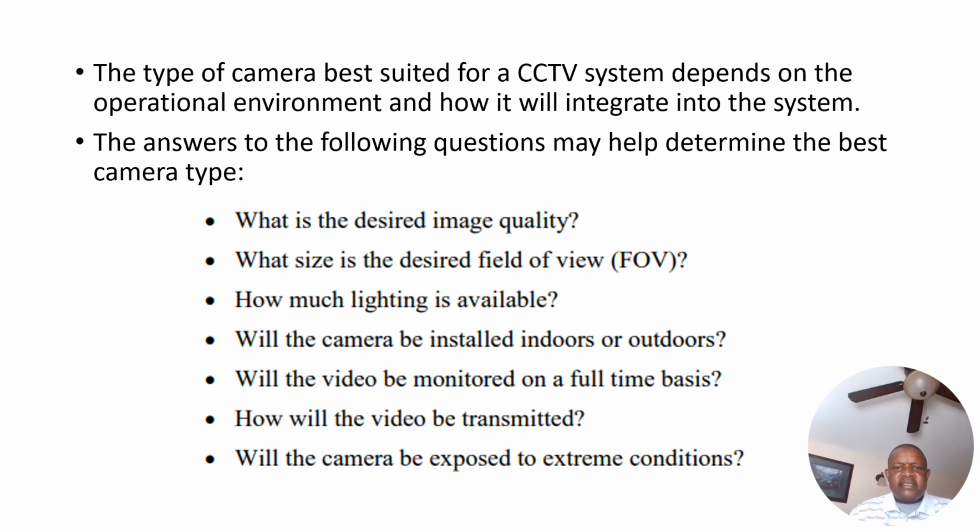What is the desired field of view? How much lighting is available? Will the camera be installed indoors or outdoors? Will the video be monitored on a full-time basis? How will the video be transmitted? Will the camera be expected to be exposed to extreme conditions?